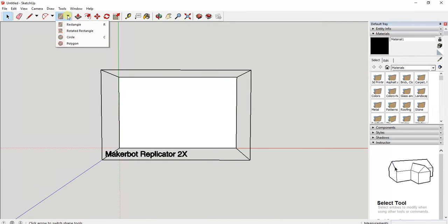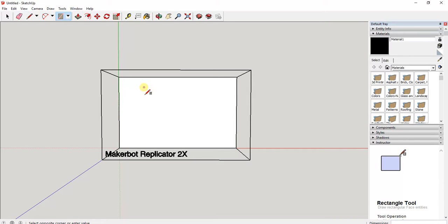We've got our basic shapes here. Here's our polygon, circle, or rectangle. You make your selection there. And I'm going to do a rectangle to begin with, make it nice and easy. So I could just click and drag and hopefully get pretty close to 10 centimeters by 10 centimeters. So again, it's in millimeters, so you'd want 100 millimeters to make 10 centimeters, but this is pretty tricky doing it by hand. It's not the easiest thing to do. We can see our measurements down the bottom right here. They are a bit cut off by the camera, but you can see that they're there.